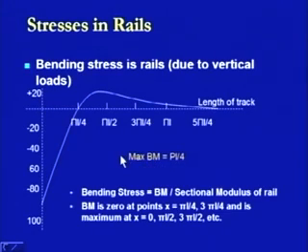With this bending moment, the variation is in this form: if it is assumed by sign notation as negative on this side, then after a certain point, which is termed the point of contraflexure, it will change its sign and become positive on this side, attain a maximum value at some distance, and again come back and become 0 along this length of the track.